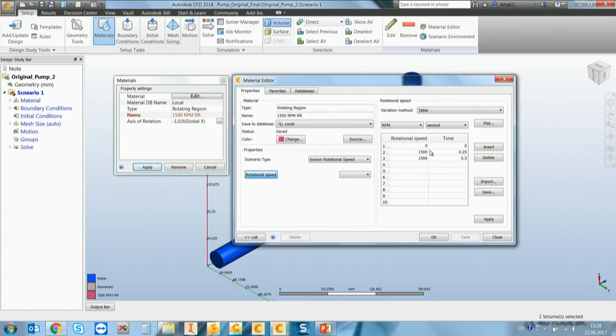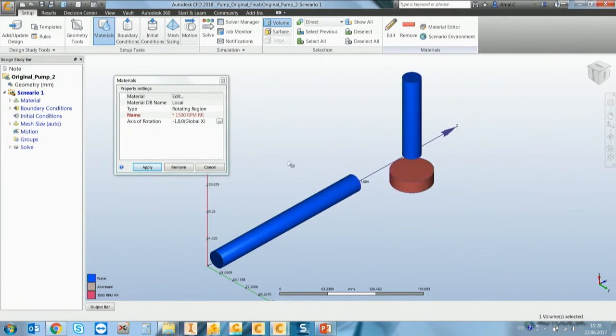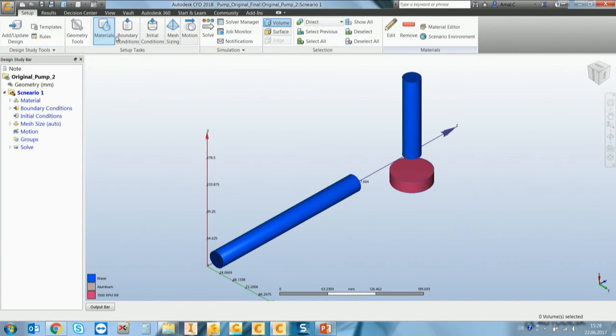So for the rotational speed, you really have to make sure that you ramp up these rotational speeds. A best practice that we noticed is that when we ramp up rotational speed over 50 times step size, it's more stable and gives more accurate results. So this time should be 50 times the step size. This time step size is calculated automatically according to the value of the rotational speed. Okay. Then everything is on here. We will move to the boundary conditions.